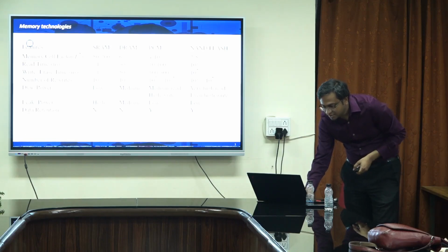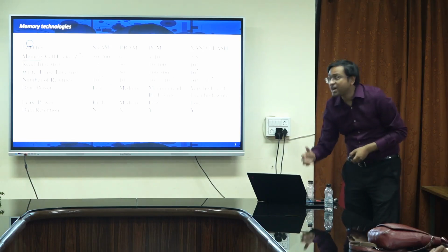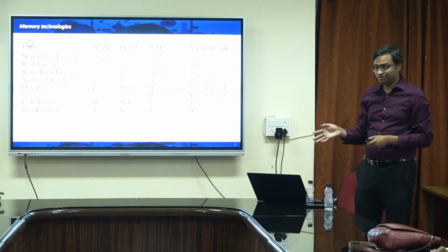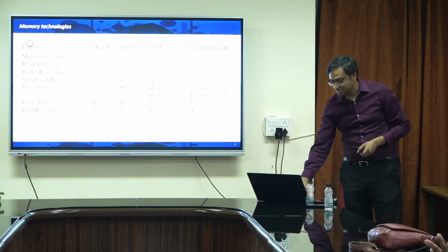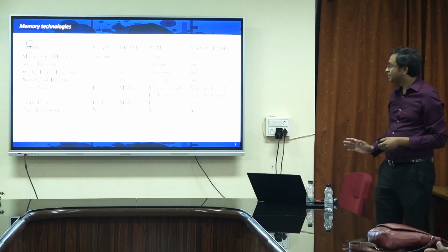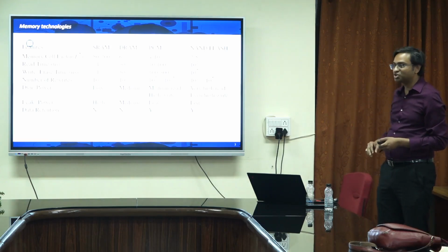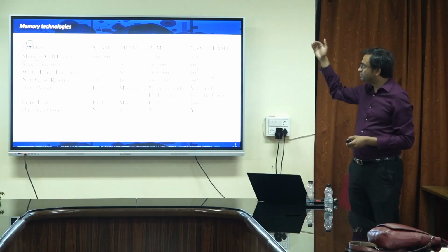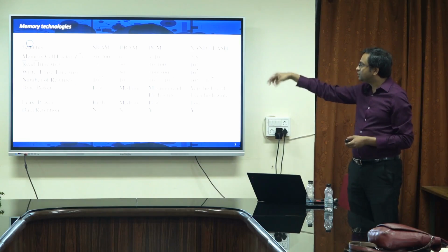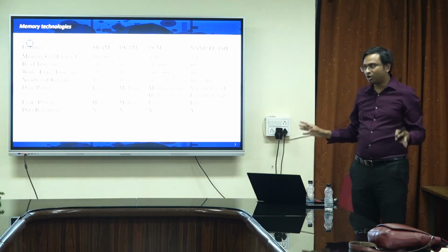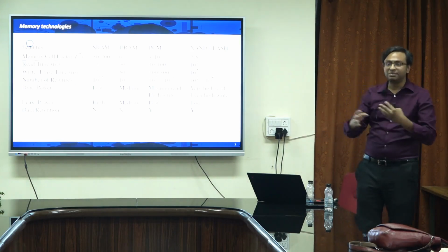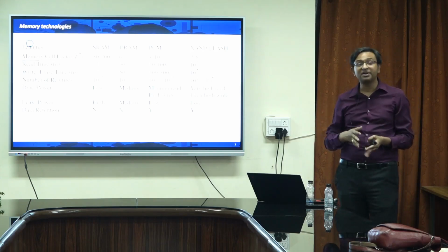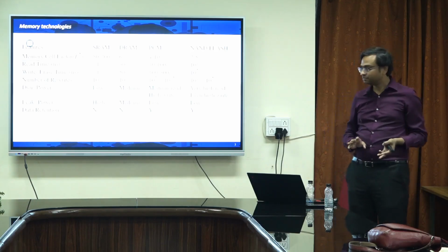While if you go to the write and erase speed, over here you see SRAM is the fastest, nanosecond, right? While look at your flash and your DRAM, very slow, right? It's like microsecond or millisecond, correct? So although you want the speed to be the highest and the memory cell to be the smallest, no technology gives you all the things, and that is why we have multiple different technologies available today for different applications, right?